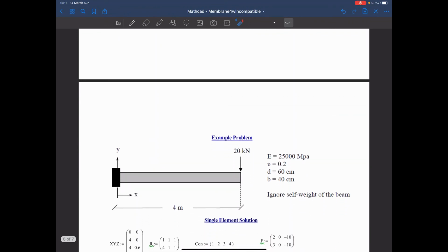Of course, let's now take a look at the same example problem. If you remember the bilinear example, we were getting 20 times smaller displacement because it's very stiff, it locks and it gives us very stiff behavior. Now the actual tip displacement, let's write it here, exact, is equal to 0.00237 with no shear deformation.